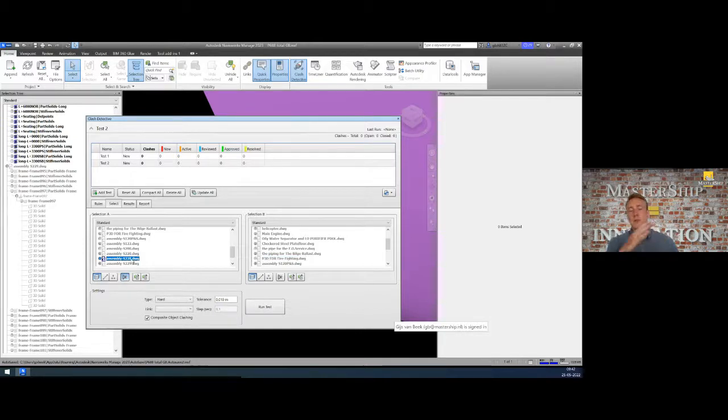But you can also look for internal collisions in section 228. So that's, for example, a bracket intersecting the hull, or a stringer going through a bulkhead, things like that. So what we are going to do, we are going to look at section 228 again, and then self-intersecting, and then we give it a tolerance of 10 millimeters in this case. So you can also say we make a tolerance of 1 millimeter, 10 or 20 or whatever.